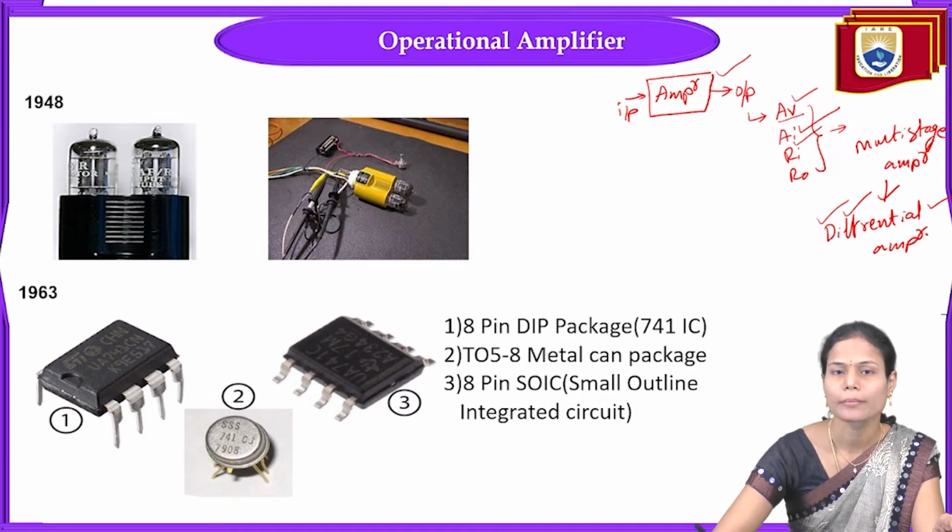That is, the collector resistances of both the transistors are the same, the emitter resistances of both the transistors are the same, and the biasing conditions of both the transistors are also the same. In such a way, we take two transistors and interconnect them with a common supply, so that we can form the differential amplifier. What is the basic function of this differential amplifier?